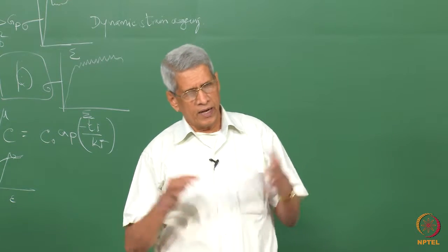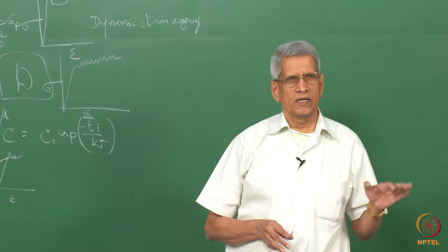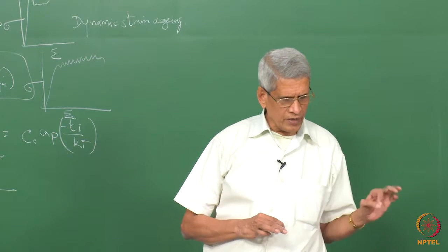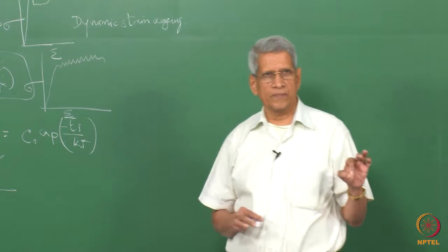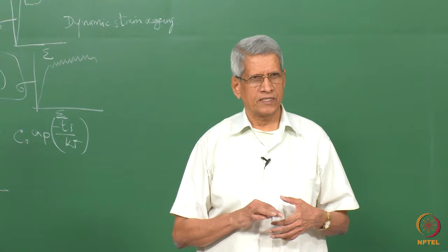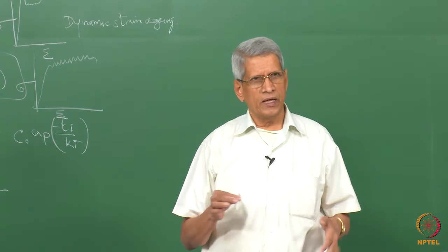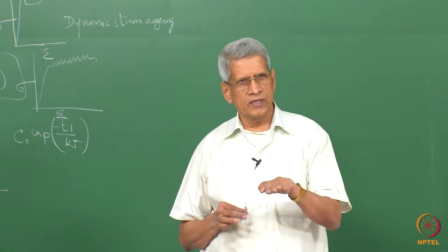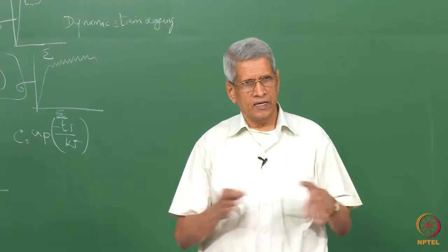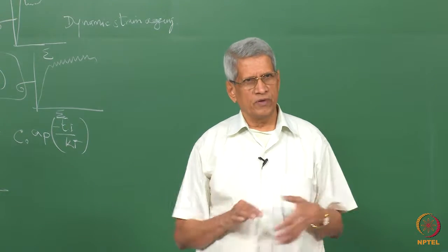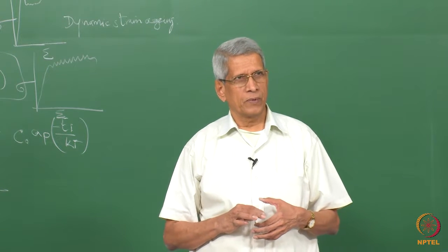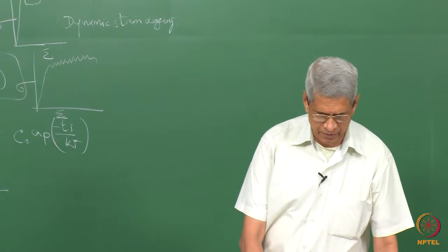There are some cases which have been observed, like in stainless steel, where sometimes this itself gives rise to what is called dislocation channeling. A softening of the material is noticed when you do subsequent mechanical testing. That is thought to be because these defects interact with the dislocations which have been generated. They annihilate and create a channel which is free of defects, within which the subsequent deformation could propagate. Okay, this is one of the things.